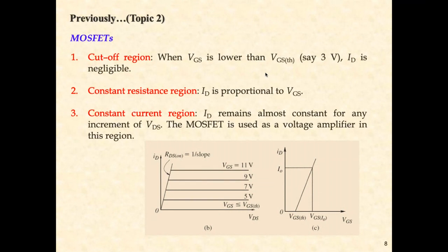And so we learned the details for how to operate MOSFETs in the converter. In general, MOSFETs for its operation region can be classified into three regions. For the power electronics interface, we only use the first two regions. And then how to determine what is happening during the regions? You just need to look at VGS, right? VGS.